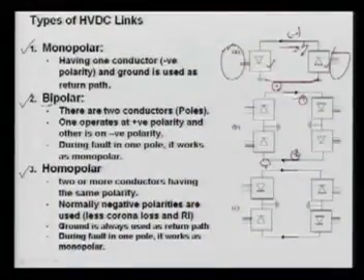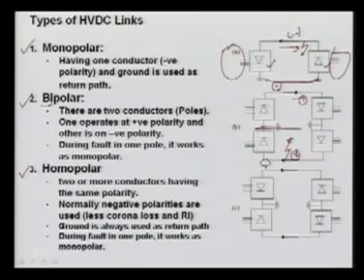So in this bipolar, as I said, the two poles are here. The major advantage is that, let's suppose one pole is faulted. We can stop the operation of this one pole, and then we can operate the bipolar just like a monopolar, meaning we can use ground as the return path, and then we can feed half of the power during the emergency condition.